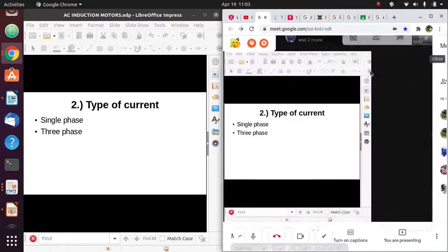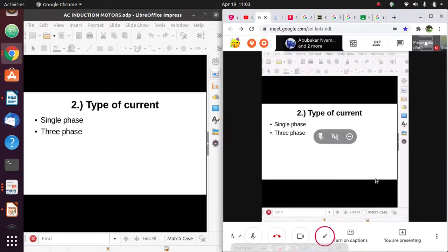Single phase is supplied in like 3 core wires, in 3 different wires. Single phase ama 3-phase? See, 3 phase has got 3 live wires, and single phase has got 1 live wire. Yes. Essentially, it just depends on the type of application, but single phase will have 1 phase wire and a neutral. And 3-phase will have 3 phase wires and a neutral and earthing. All of them will have earthing.